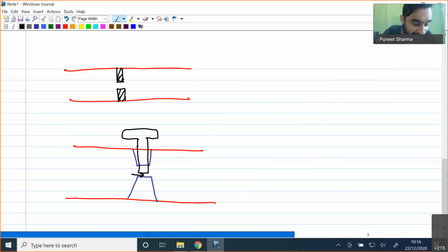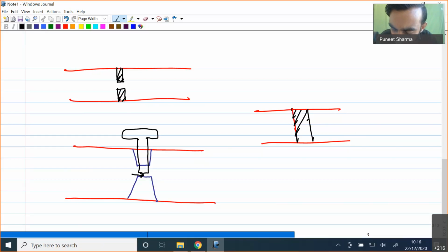Okay, sometimes we also put some porous material in our pipe. If we put a porous plug in our pipe, that porous material can also act as a throttle, because through these pores we will have a significant pressure drop.